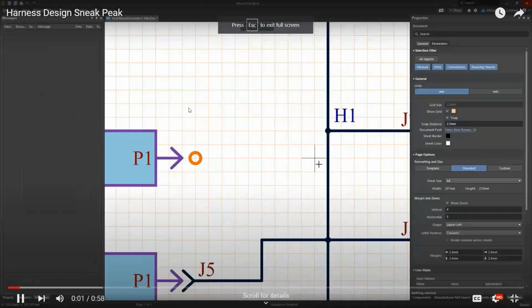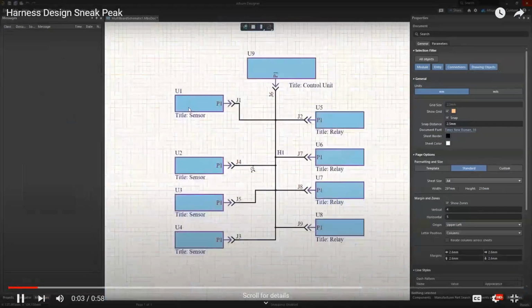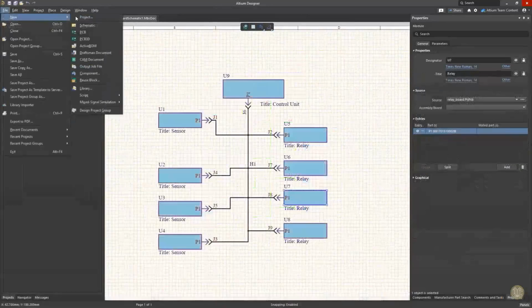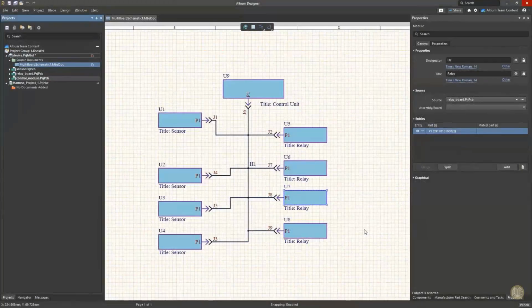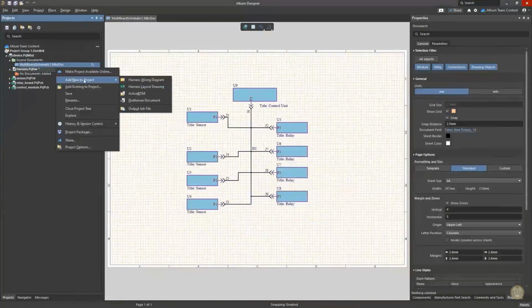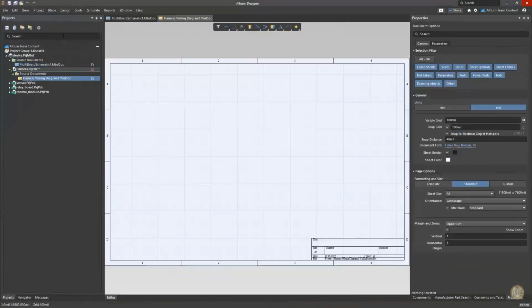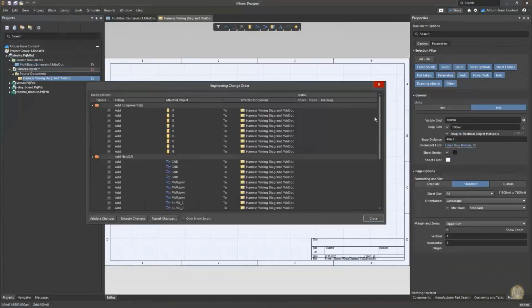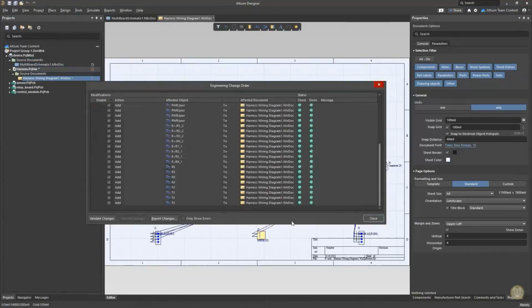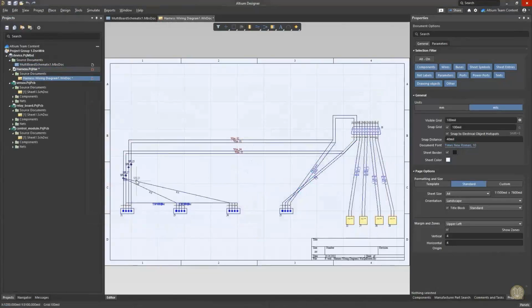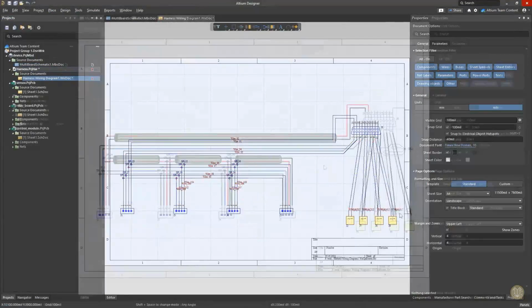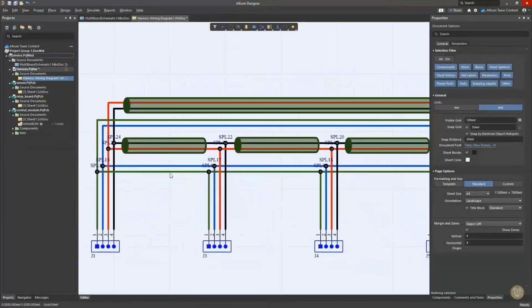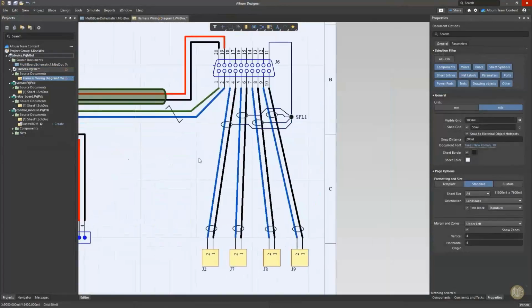Just completed your multi-board project. So what's next? The answer is harness design. This release of Altium Designer introduces new design capabilities in the form of a harness project. Now, you're able to develop harnesses and cable assemblies for your devices. Use the data from a multi-board project to form connections between the connectors. Assign a wire to each connection, specifying the necessary parameters. Specify design features such as stranding, shielding, or the use of a prefabricated cable.